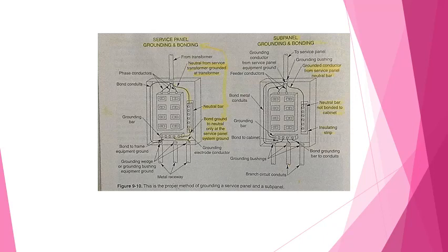equipment. Such situations exist whenever defective, worn, or misused equipment is handled by the operator, especially in damp or wet areas. A ground fault circuit interrupter, or GFCI, is a device that opens a circuit if an unusually large current to ground is detected. Having this device in the circuit is a way of preventing shock hazards when poorly grounded equipment is operated. For this reason, the NEC requires GFCI protected circuits at the following locations.